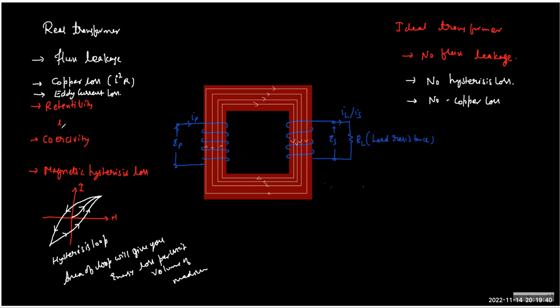That is why an iron core is designed by taking thin sheets of iron and sticking them together to create this entire shape. You can think of it as coasters. You take multiple coasters, put one over the other, and make a stack, and every coaster is isolated from the others.